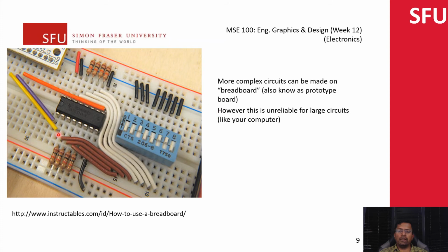You can create a more complicated circuit, what's known as a printed circuit board. This is what's known as a breadboard, where you can connect components. The way this is created is that all of these pins along the width are connected. So these pins are connected, these pins are connected. The pins to the left and right aren't connected as such. All of these are connected and all of these are connected.